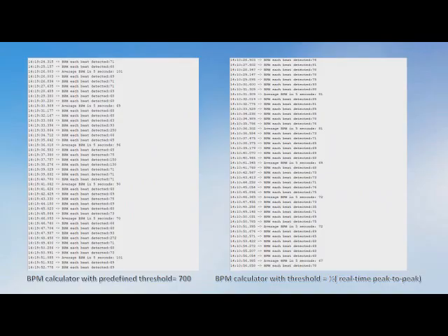We tested both of the methods. The first one, with a predefined threshold, can achieve a reasonable heartbeat with a correct threshold, but is outperformed by the second method in terms of precision and accuracy. The value shown here is the calculated BPM after encountering one cycle, which is used in the testing phase, while the BPM displayed on the watch will take the average of the BPM readings over 5 seconds.